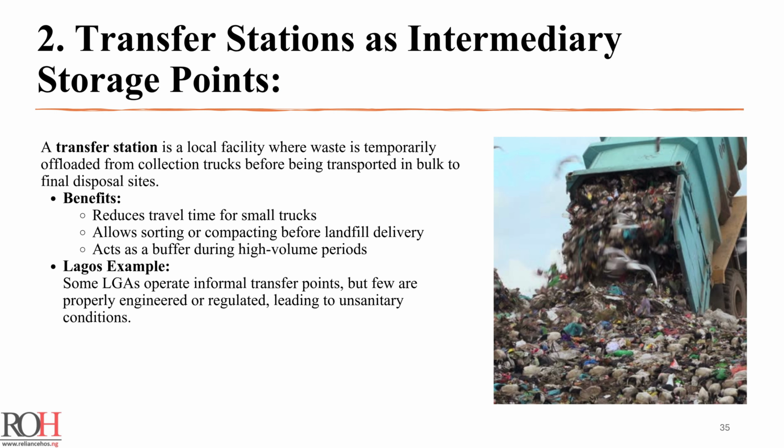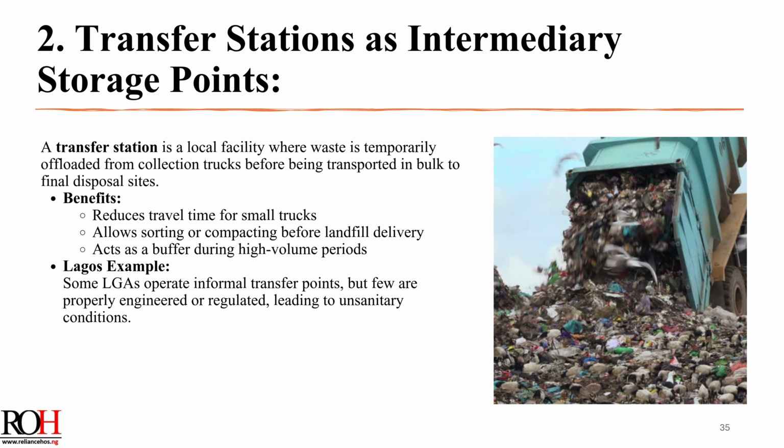2. Transfer stations as intermediary storage points. A transfer station is a local facility where waste is temporarily offloaded from collection trucks before being transported in bulk to final disposal sites. Benefits: reduces travel time for small trucks. Allows sorting or compacting before landfill delivery. Acts as a buffer during high-volume periods. Lagos example: some LGAs operate informal transfer points, but few are properly engineered or regulated, leading to unsanitary conditions.